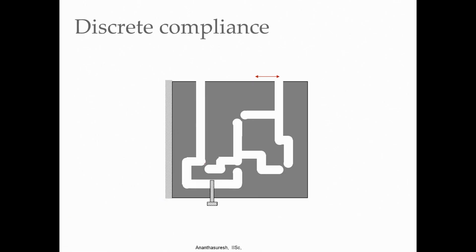So, all these are elastic pairs, we have joints there, right, they are the elastic pairs. In fact, we had said that this actually comes from a 4 bar linkage. If I apply force over here by turning the screw, this is going to move like this. If I move it back and forth, the screw after it touches, I can make this move.